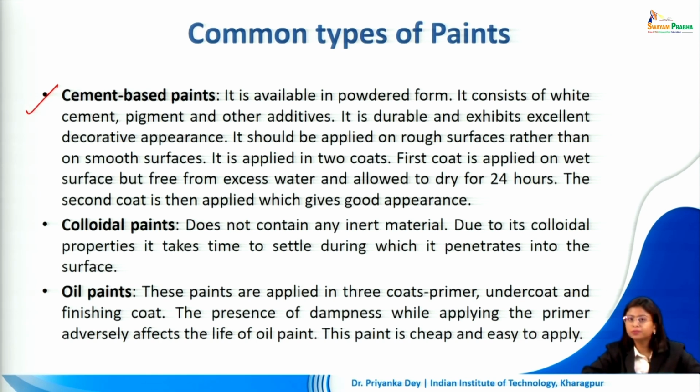This is very durable and it exhibits an excellent decorative appearance. It should be applied on rough surfaces rather than on smooth surfaces, and it's usually applied in 2 coats. The first coat is applied on a wet surface which is free from excess water. We allow this surface to dry for 24 hours. Then the second coat is applied, which gives the final finished appearance.